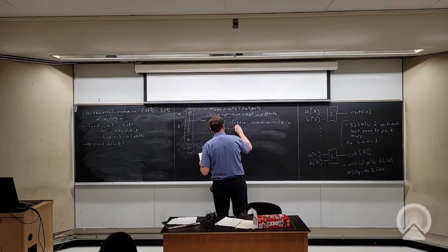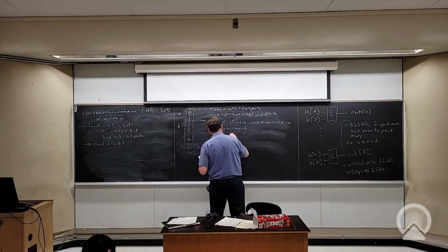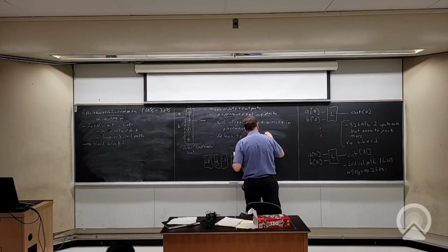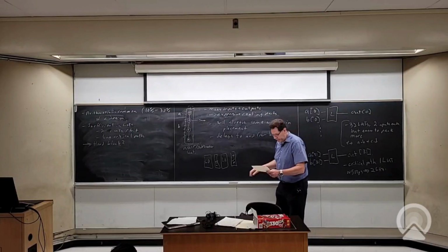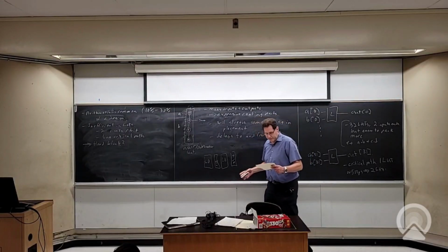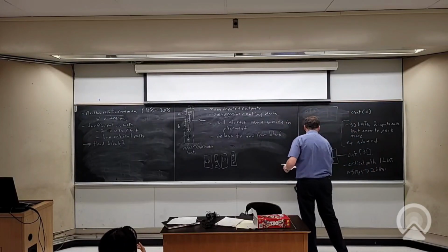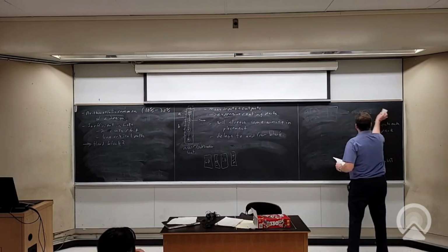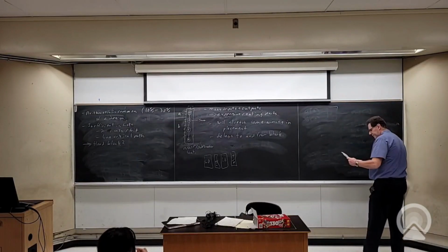Okay, so stretch some wiring in placement, and that's going to lead to some increased delays to and from the block, because it will tend to not be quite as close as the next logic block would have been. Now, if I had no better ideas, I should still actually do this, because it does solve my critical path problem. Or I would probably still wind up doing this. But maybe we can come up with a better idea.